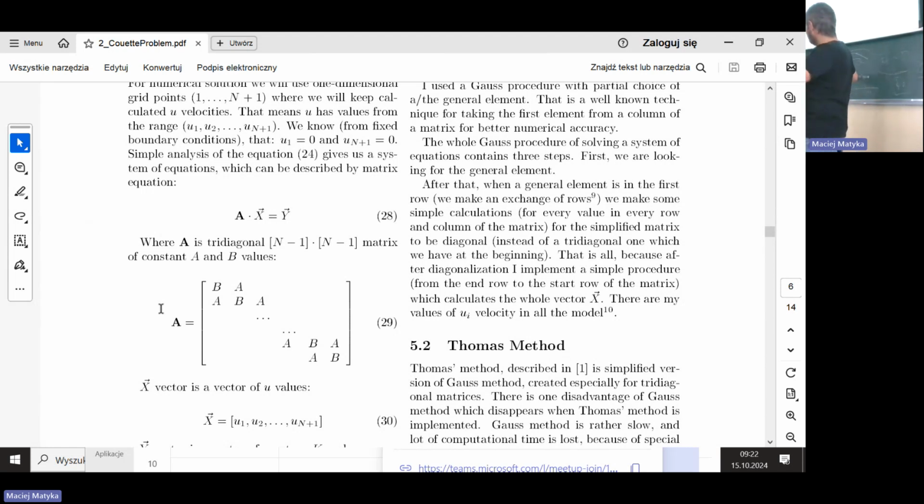And if you make a physical experiment in a tunnel, and the Reynolds number is low enough, then this pressure term will not take any part, and the solution will be like this. So this is not a hypothetical situation. This is something that happens. In very many situations, the linear flow is visible.